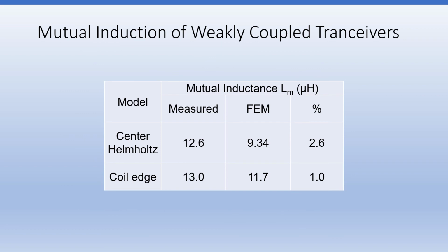For the mutual inductance of an asymmetrical coupler, where the size of the receiver was much smaller than the size of the transmit coil, the discrepancy between the result calculated by finite element method and the experiment was now about 3% only. This is also due to the homogeneous multi-turn coil used in the finite element model, while in the actual experiment, litz wire was used to minimize the skin and proximity effect. The error was smaller due to the large transmit coil diameter compared to the receive coil.